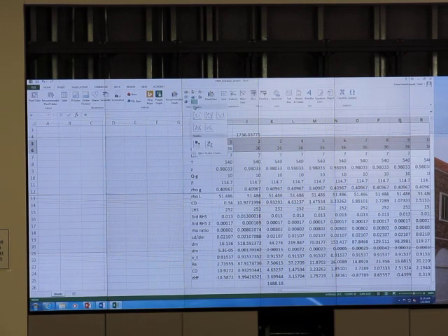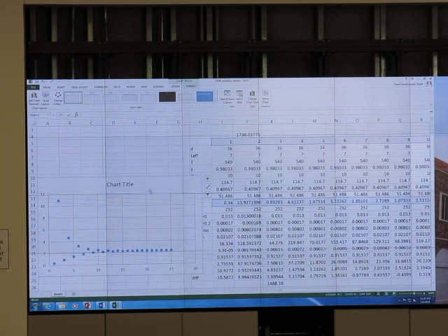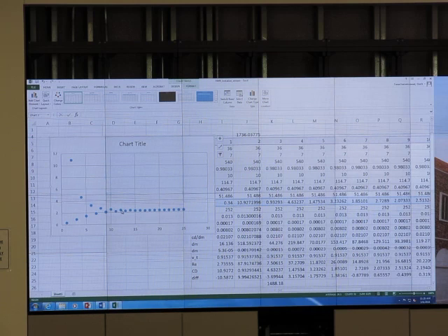Let me show you a graph. I show this C_D value, output, versus number of iterations. We input 0.34, it goes up, goes down, fluctuates a little bit, and after 10 or 12 iterations, we approach 0.225. At 25 iterations, we get 0.23 or something.